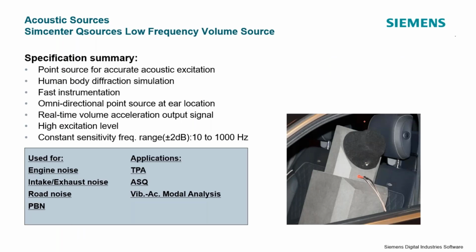So even if you have transfer functions down to the lower end of the hearing range at 20 hertz, you can adequately drive your structure. I have personally used one of these to measure the transfer function on the frame of an automobile. And when someone told me I could use an acoustic speaker in the driver's seat with the windows closed, play a noise and measure an acceleration on the frame of a full-size truck and get a decent measurement, I thought they were crazy.